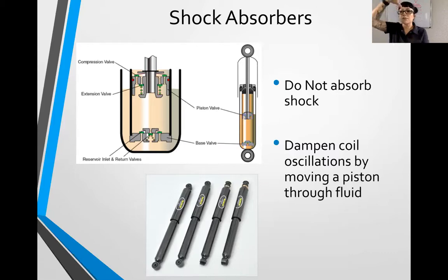Well, we don't want the spring to be continuously doing that because a spring can do that for a long time, especially if it's pushed really far. If you had no shock absorbers, you would be driving your car and you'd go over a bump and it would just continue to keep bouncing, even though you went over that bump quite a ways back. You're still going to get that leftover oscillation, and it'll get softer and softer until it's done. And then you go over another bump and the same thing happens. That is why we need shock absorbers. So shock absorbers are going to help limit the amount of times we get that bounce.